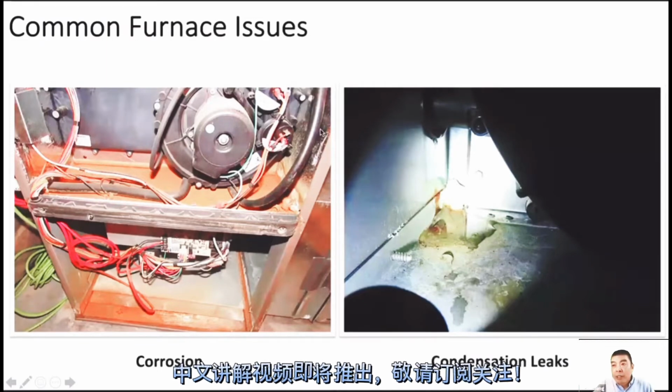Okay, so then we see the common furnace issues. Like these pictures, I think most are from the job site. Yeah, I met all those problems. So this one, the corrosion. The corrosion, or the rust, we normally find in the high efficiency furnace.